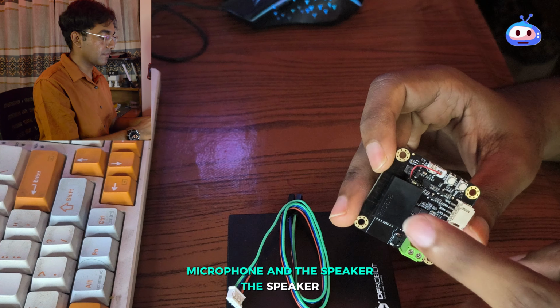First, the ambient light sensor. Select the Arduino file and connect the board to your PC. This code is pre-written to detect the lux value of the room. Before building it, select the ESP32-S3 board in the tools: go through ESP32 and choose ESP32-S3 Dev Module, and you must enable USB CDC on boot.